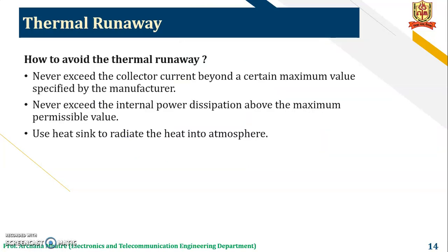So how to avoid thermal runaway? Never exceed the collector current beyond a certain maximum value specified by the manufacturer. Never exceed the internal power dissipation above the maximum permissible value. Use a heat sink to radiate the heat into the atmosphere.